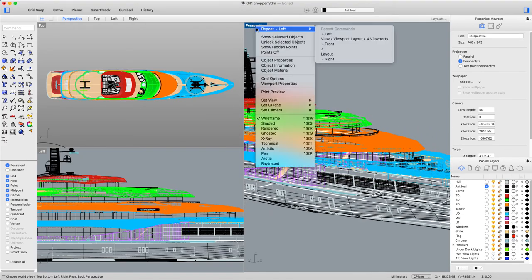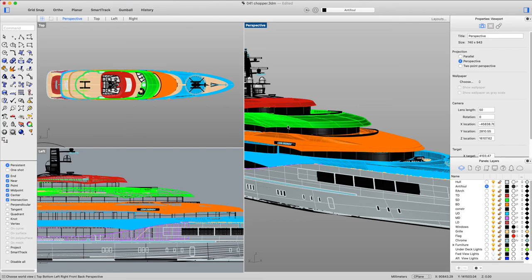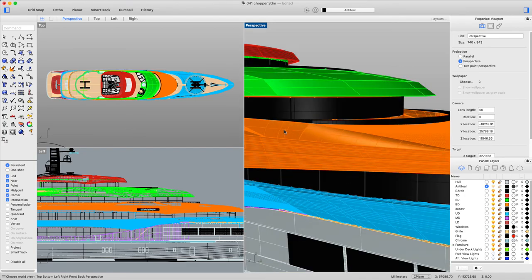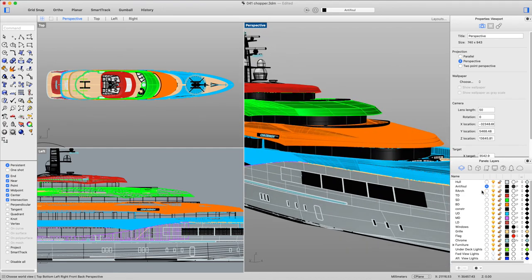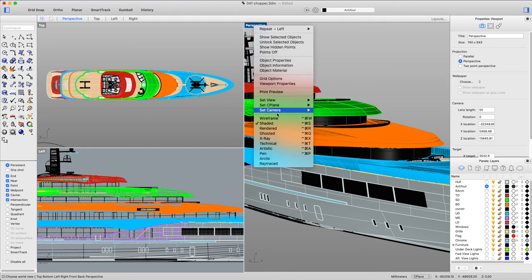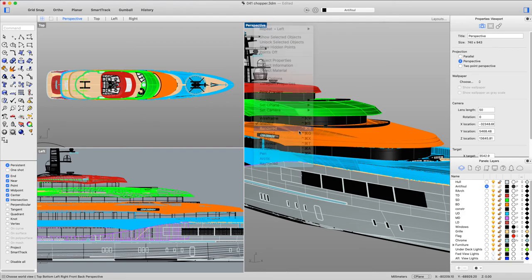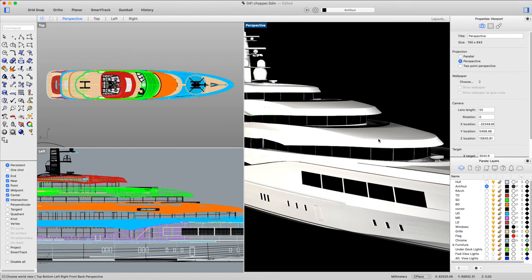If I want to see it in 3 dimension, in a shaded kind of view, I would have to choose one of these. Shaded gives the surfaces that you've got some color. These are color coded to the different heights of the thing, which is why they're all crazy colors. Rendered applies the materials that you've put on.